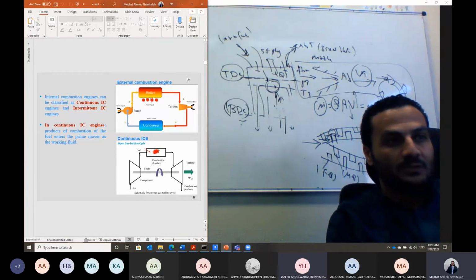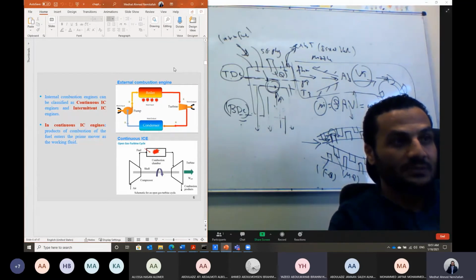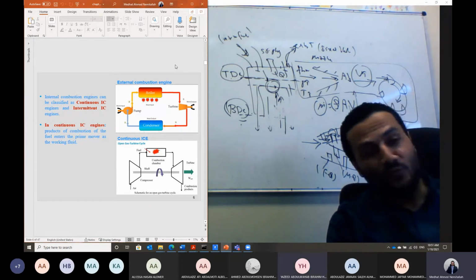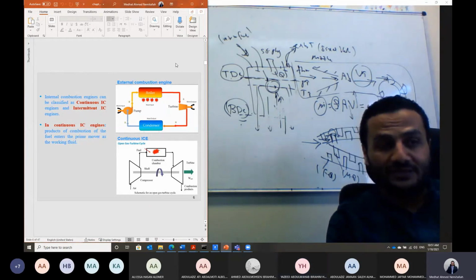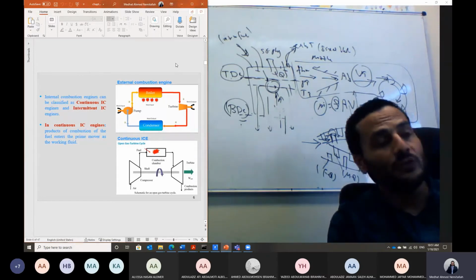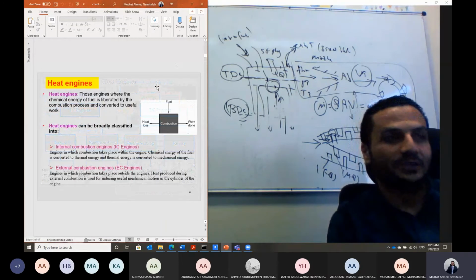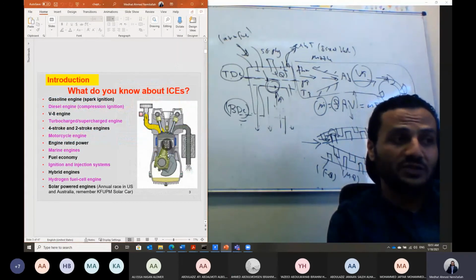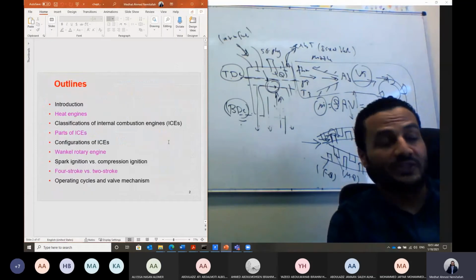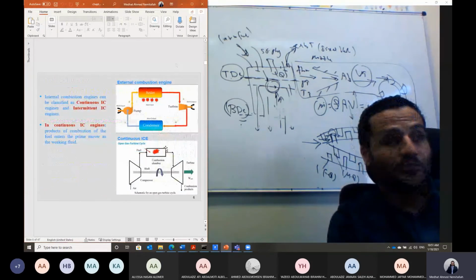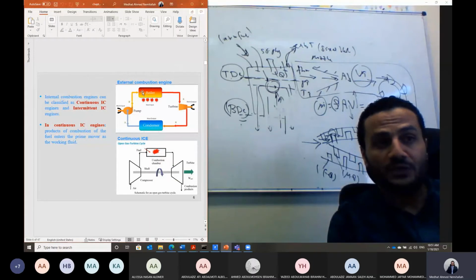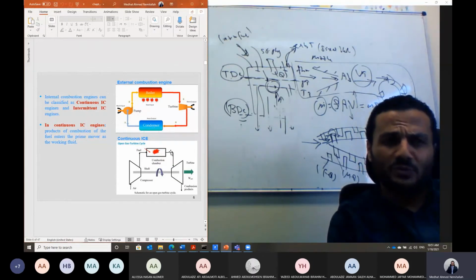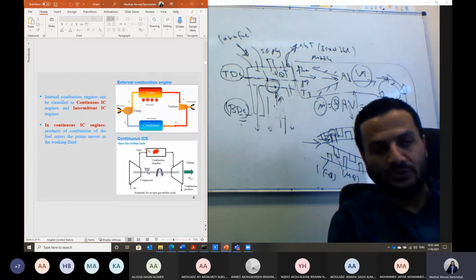In internal combustion, we have the ignition spark. Internal combustion means we are burning the fuel within the same unit in which we generate the shaft power, like here. In an internal combustion engine, we burn the fuel to generate heat, then we generate shaft power within the same unit. But external combustion means we burn the fuel in one unit and then generate the shaft power in another unit. Gas turbine, guys, is classified as continuous combustion.